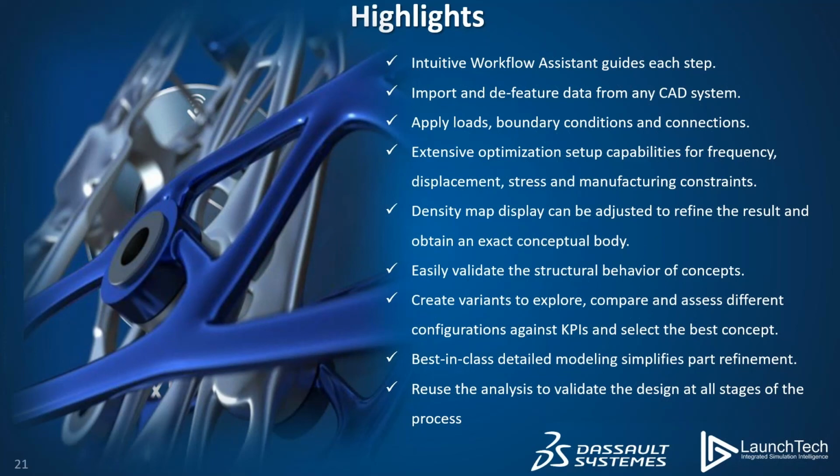You can even import a CAD which was generated in some other software into the 3D experience platform in STEP or IGS format, and then do the de-featuring of it. And then you can apply your loads, boundary conditions, and define your connections. You can do extensive optimization setup for frequency, displacement, stress, and you can define the manufacturing constraints.